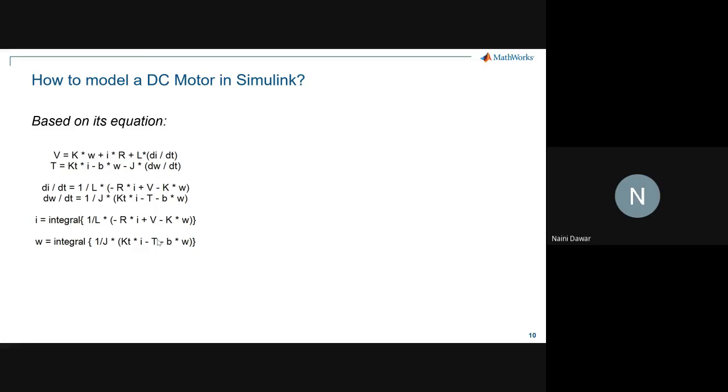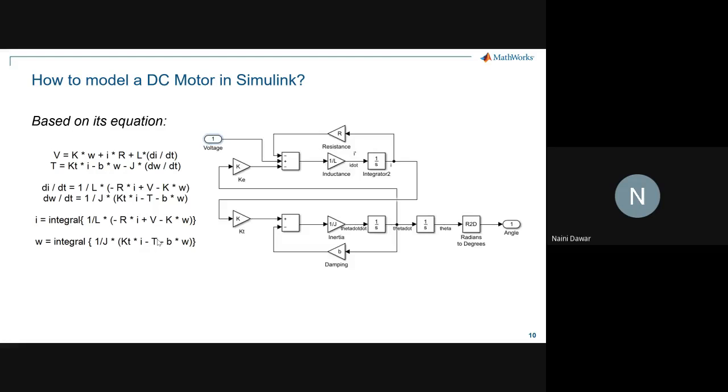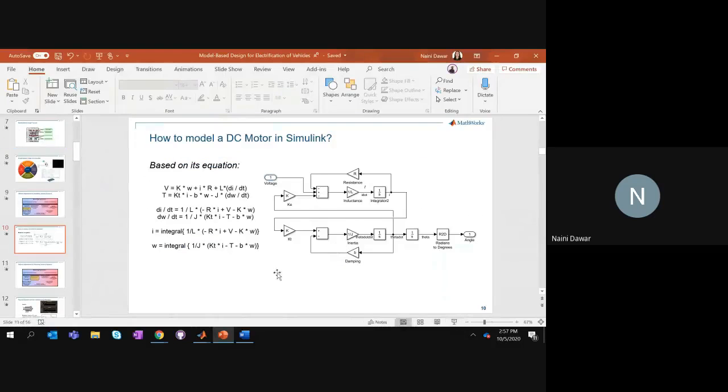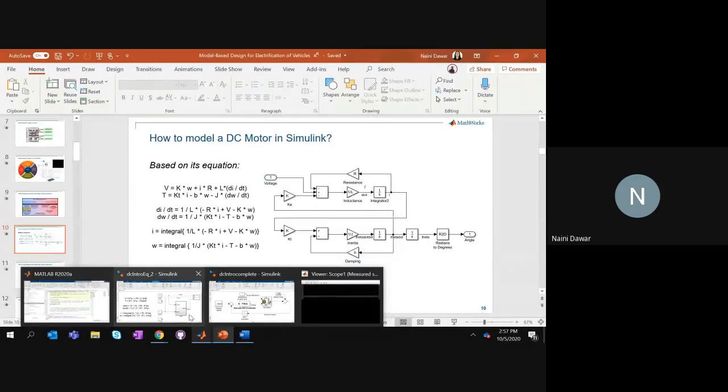And if we have to model this in Simulink, as we said, Simulink has a graphical environment. It has built-in library blocks with which you can model and simulate your dynamic equations. Now, in this case, this is basically a differential equation, and we have used the mathematics library from Simulink to model this particular equation, right? To show this in action, I will open up the Simulink model.